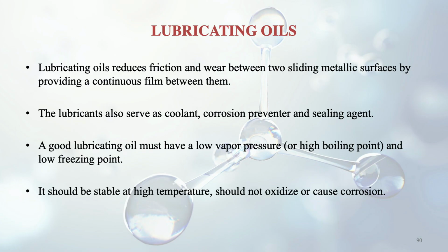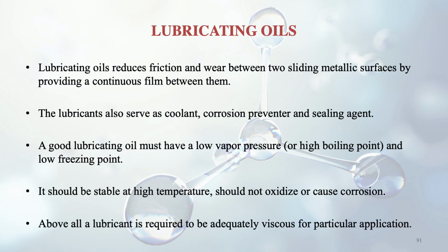That's why we need low vapor pressure or high boiling point, and obviously low freezing point, because otherwise it will be a solid. And it should be stable at high temperature, obviously, and should not oxidize or cause corrosion. Because at high temperature, if it breaks down, then it cannot be used any further. Above all, a lubricant is required to be adequately viscous for a particular application. We have seen this earlier also.